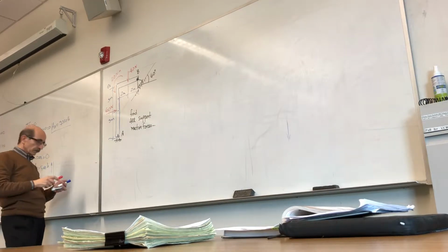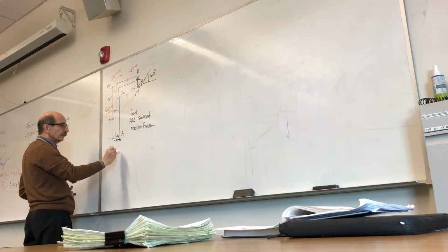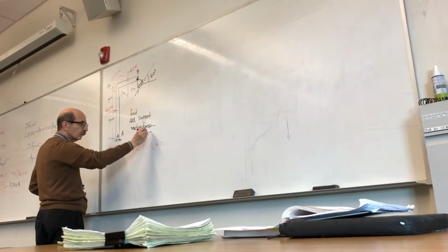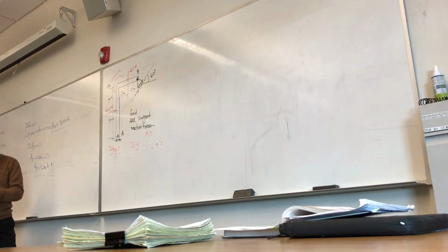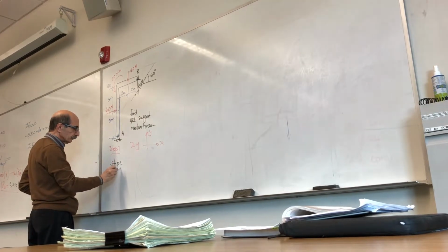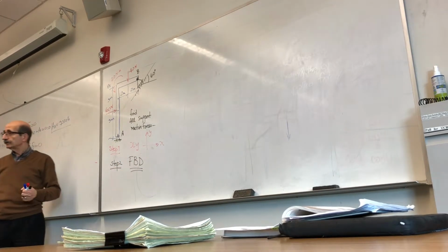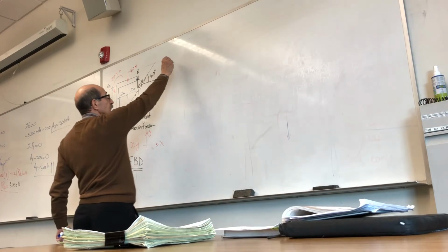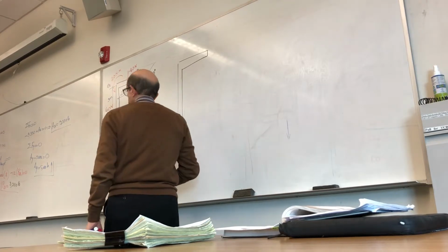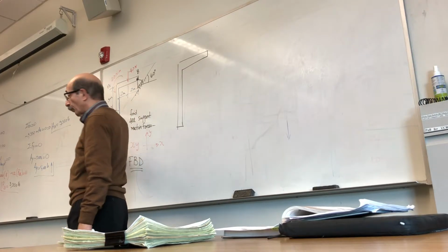So steps are, as I said, step one, you just set up the X and Y coordinate, X and Y. Step two is the heart of rigid body equilibrium analysis, free body diagram. You cut the structure from its supports, replace back the effect of these forces that supports represent.